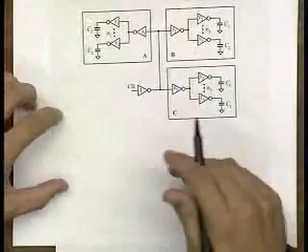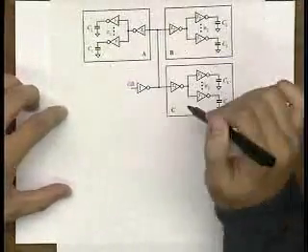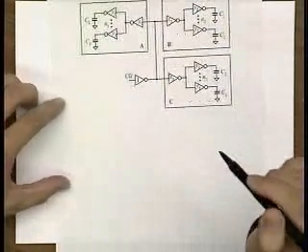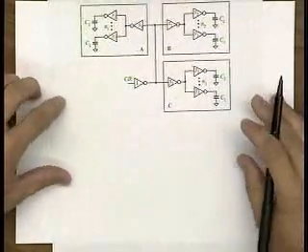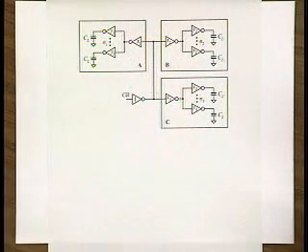So what you need to do now is you have these different clock domains. You notice that if you want to minimize the delay in the worst case, the fair thing to do is to think this way. If I want to minimize delay in all of the branches, then all of them should be treated the same way. They should have the same fair treatment, meaning that the optimal result would be that delay in all of these subdomains is equal, right?